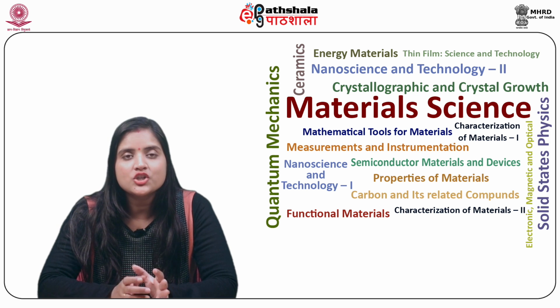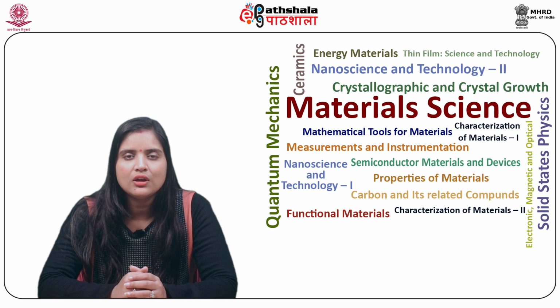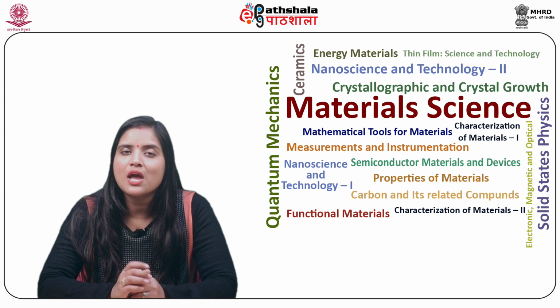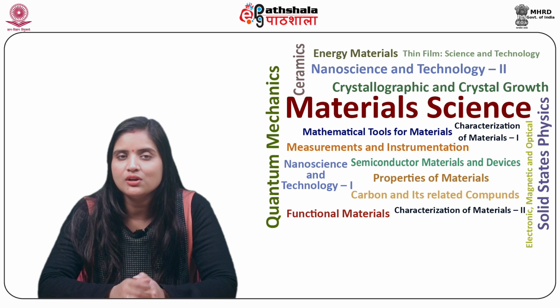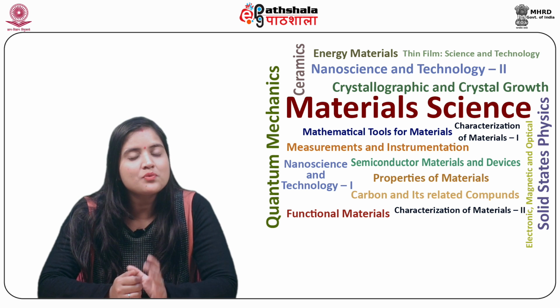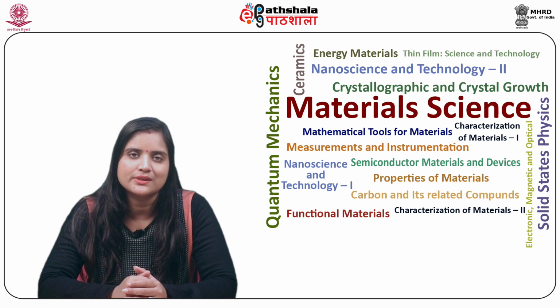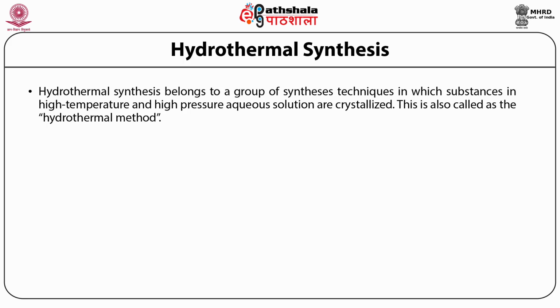Incidentally, the largest naturally occurring single crystal, that is beryl crystal more than 1 kg, as well as the largest man-made single crystal, which is quartz crystal of several kgs, both have been originated via hydrothermal process. Hydrothermal synthesis belongs to a group of synthesis techniques in which substances in high temperature and high pressure aqueous solution are crystallized. This is also called as the hydrothermal method.